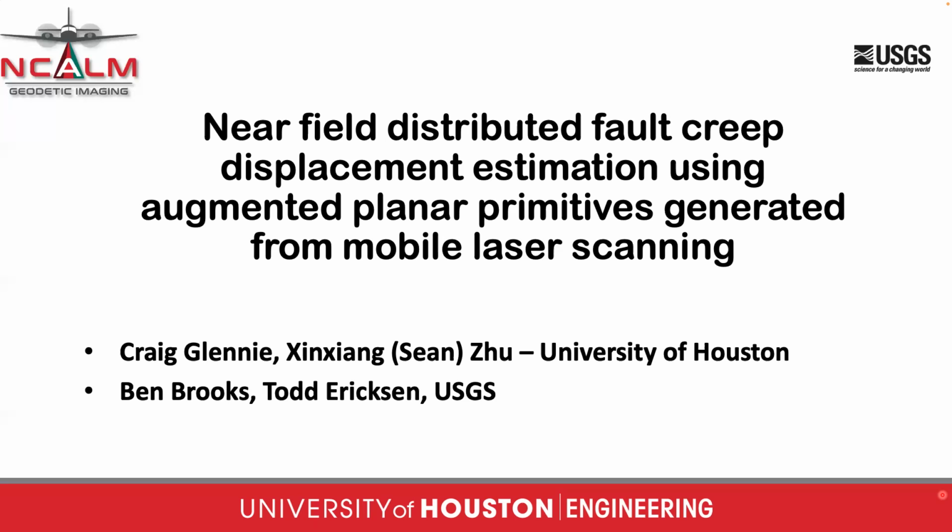As Jinha said, my background is in geomatics, but I'm going to present something that uses some geomatics tools but is really motivated more by an earth science question. That question is: how do we look at earthquake or fault deformation in something called the near field? Basically, that means the zone very near to where the fault rupture actually happens. We're going to look at using mobile laser scanning to get down to sub-centimeter level distributed fault creep in those areas.